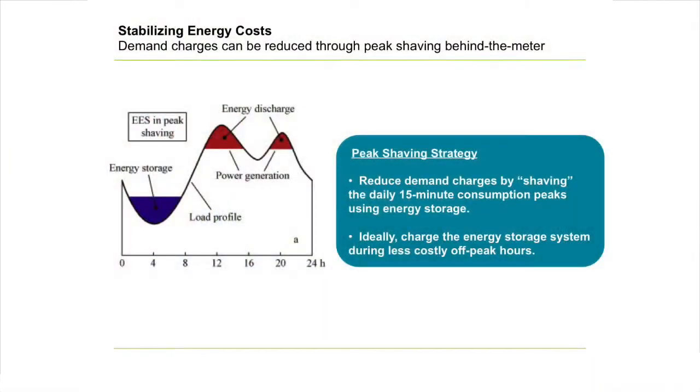So if you look at a typical load profile of a building, in the evening there's less energy consumed. People are gone, the lights are off, the computers are shut down. During the day, as people come in and start generating energy, as your lights get turned on, as your computers get started, your consumption goes up. So if you can store that energy at night, hold on to it, and then during the day when those peaks occur, fill in those peaks, to the utility, it looks like you're consuming less energy, which means you're charged less for your demand charges, which stabilizes your energy costs.